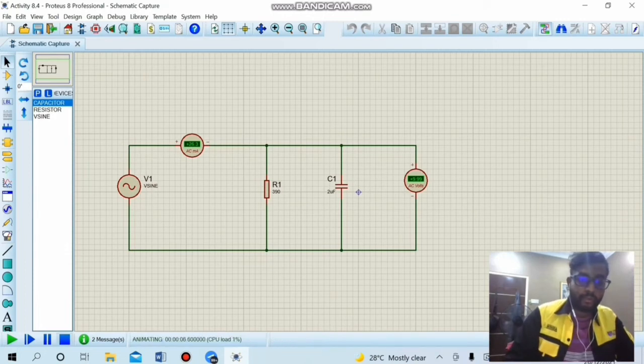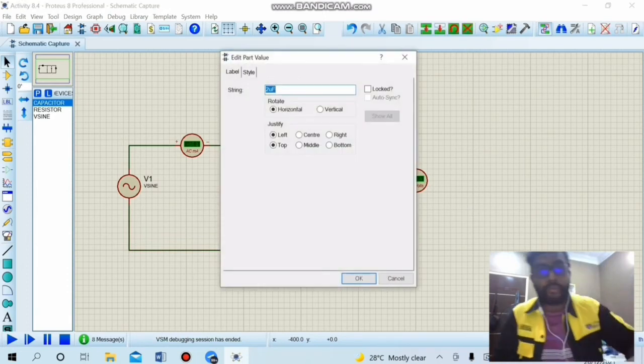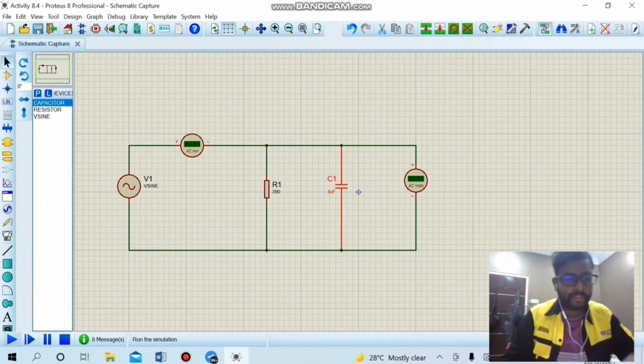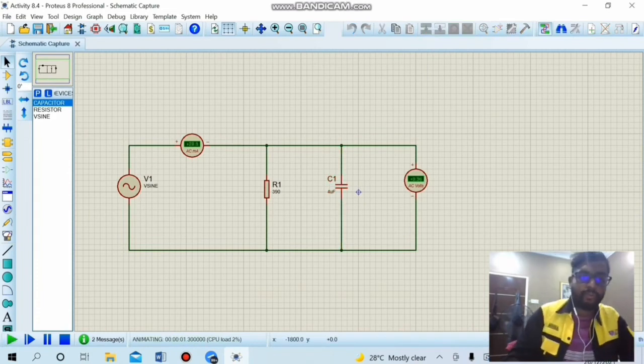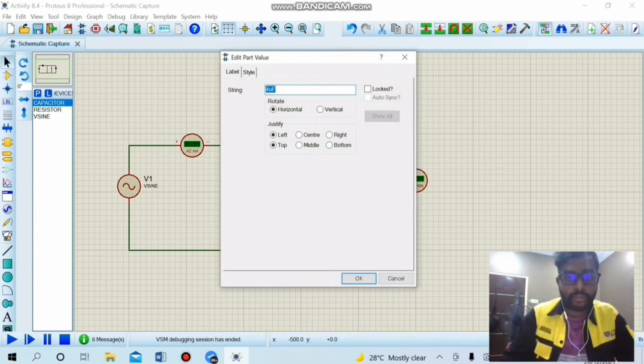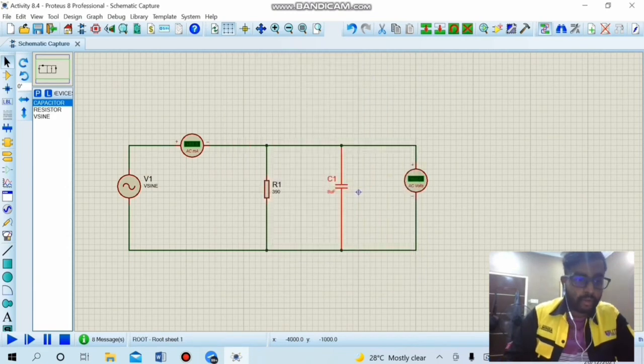For the next case, we are going to calculate for 4 µF. With the resistance kept at 390 ohms, we will get a current value of 28.5 milliamperes and the voltage is still the same, which is 9.99 volts. For the next case, we keep the resistor at 390 ohms and change the capacitance to 8 µF. Now we will get a value of 35.9 milliamperes and 9.99 volts.